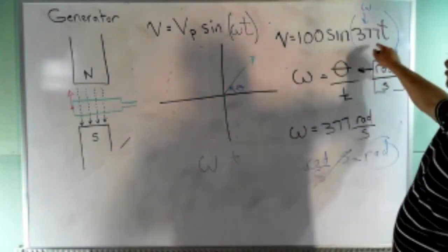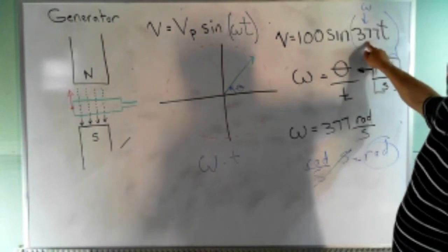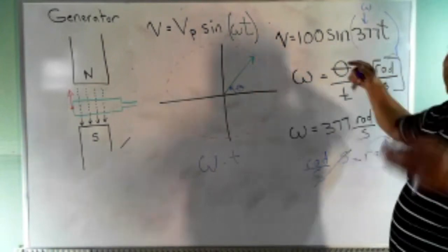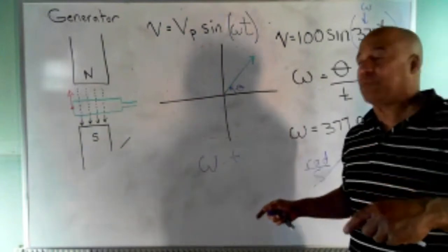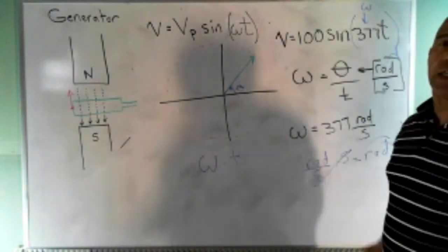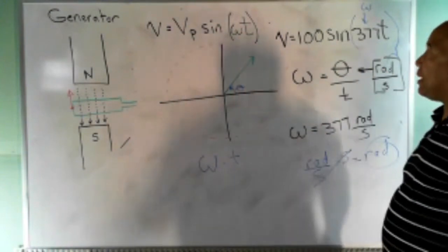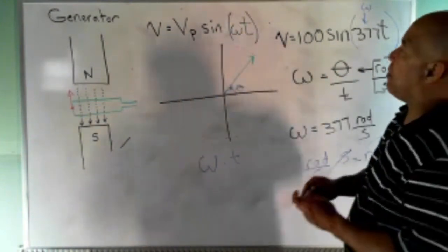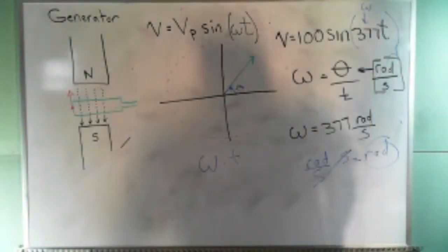That's showing you that the argument here, I'm taking radians per second and multiplying by second. The thing in the argument is radians. So when you do a calculation with this, you got to change your calculator to radians because the argument is in radians. And so the way we're going to represent an AC waveform is more like this. So it gets more interesting as we go.